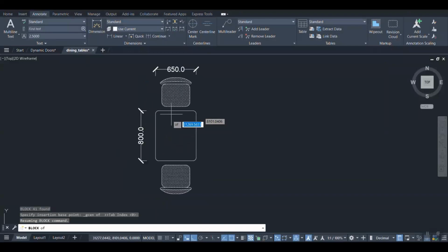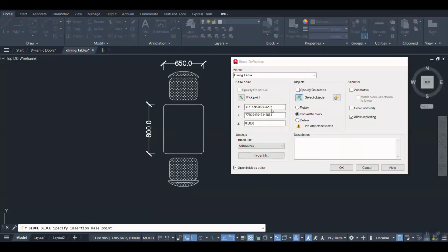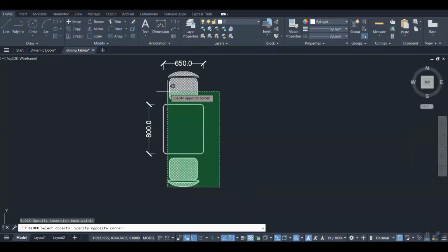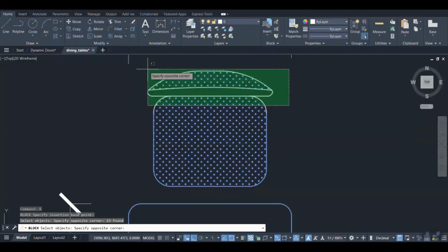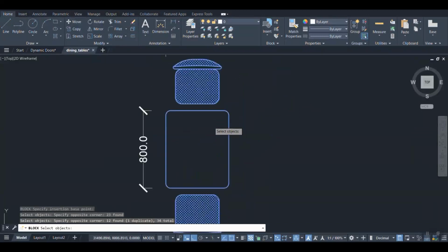Probably I am still figuring out why geometric center is not highlighted, but if you are choosing just the middle of it, you can hit the O snap multiple times, and if it's not providing it, you can just zoom in, zoom out, right? Most of the chances are zoom in, zoom out. That is one of the reasons it's not showing a geometric center, but no worry, you select the blocks again. Let me do it this way.